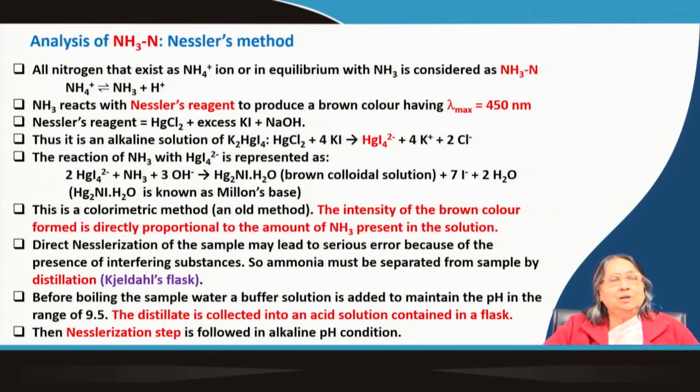So, you prepare a standard ammonium chloride solution, where, for example, 1 milliliter of that solution is equivalent to 0.05 milligram of ammonia nitrogen. You have to add it drop by drop into that blank solution where you have taken the distilled water, and then you will see when the color matches your sample water.